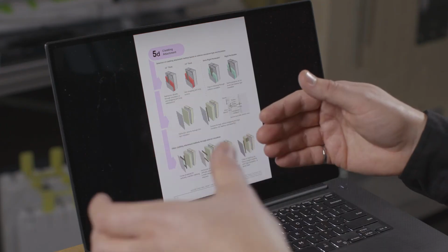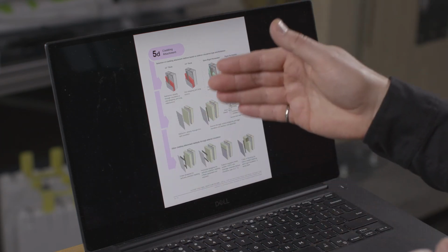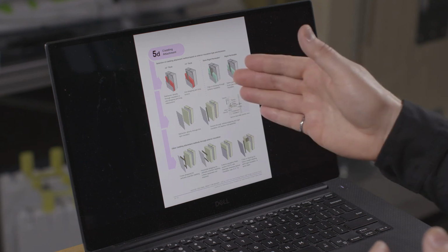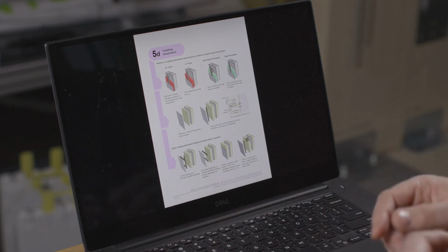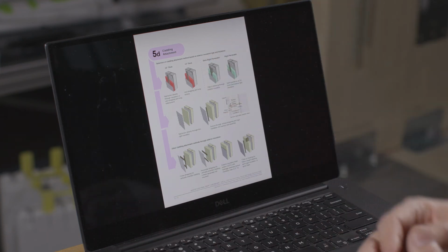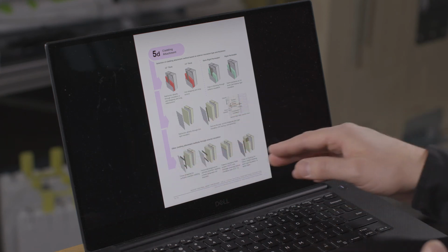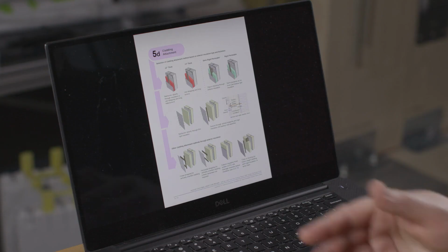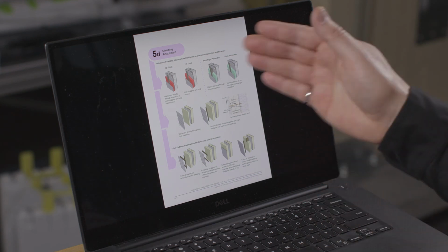And then it was talked about in the last part here. So we've got our insulation, we got the water and air barrier placed, the vapor barrier, then how do we attach cladding? And so with thinner or thicker amounts of insulation, there's guidance here around that. And it talks about long screws through insulation and how you attach cladding to strapping that is screwed through your insulation for thicker amounts of insulation. A number of alternate configurations are also talked about. If you have, say, vertical board and batten or shingles, things like that, where you need horizontal strapping, how to do that. EIFS is talked about, and heavier claddings are also mentioned in here as well.